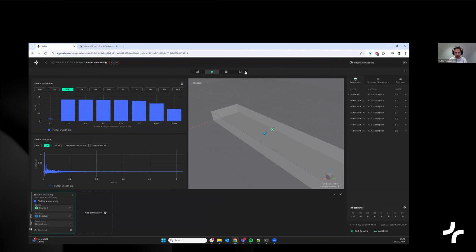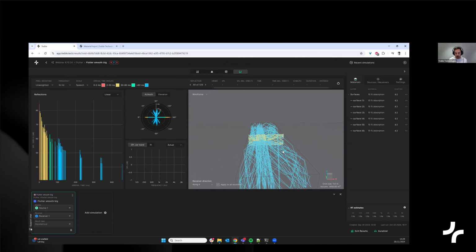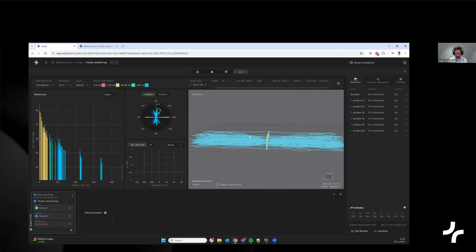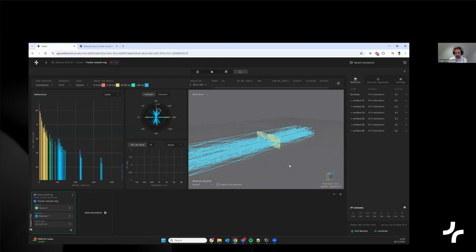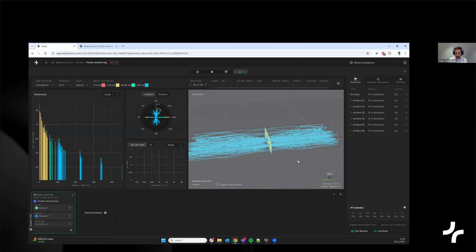And then if you go into reflection tracking, we can see that you have strong reflection here in this plane, the vertical plane. So you have kind of between the source and the receivers bouncing off all of the side walls and the floor and the ceiling, and then you have kind of along the long edges also later in time.